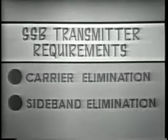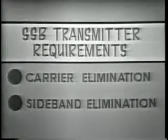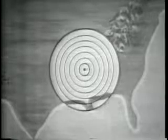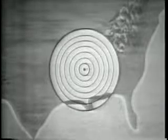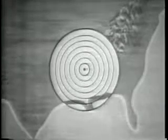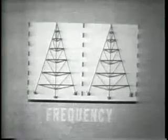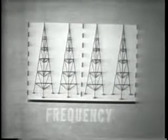A single sideband transmitter must accomplish carrier elimination and rejection of one sideband. The transmitted signal contains only one sideband with all of the power of the transmitter. This increases the effective transmission 3 times over an equivalent conventional AM transmitter. The reduced receiver bandwidth doubles the signal-to-noise ratio, resulting in an overall system gain of 6. It also decreases the required spectrum occupancy. This increases the number of stations that can now operate in the whole frequency spectrum.